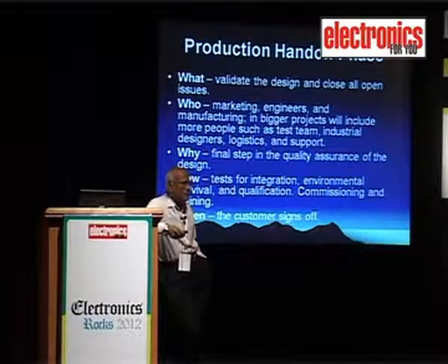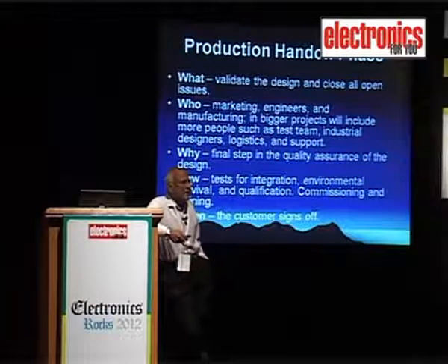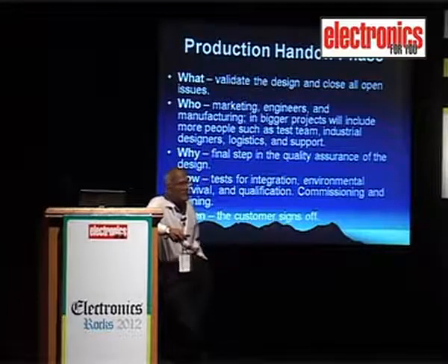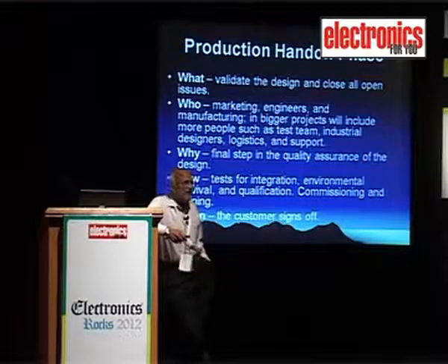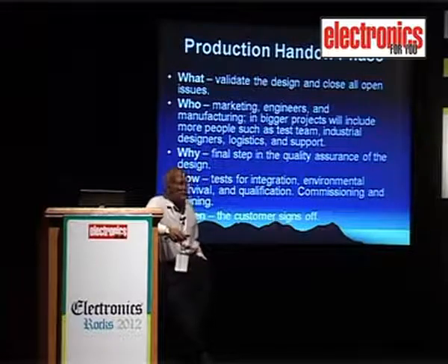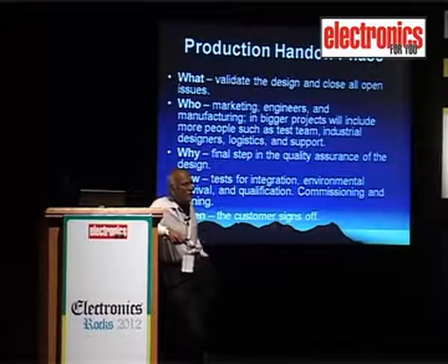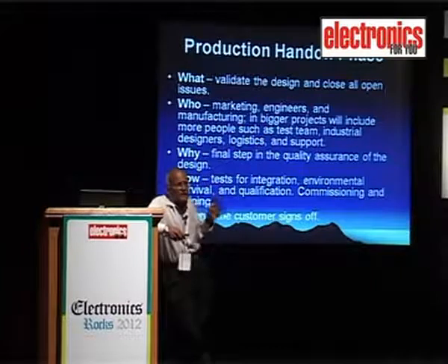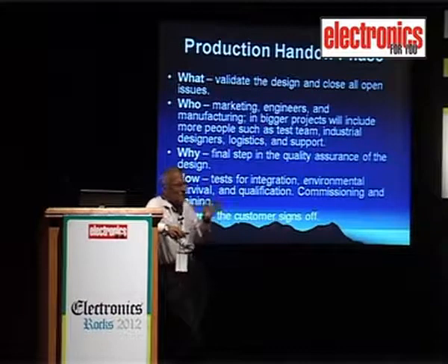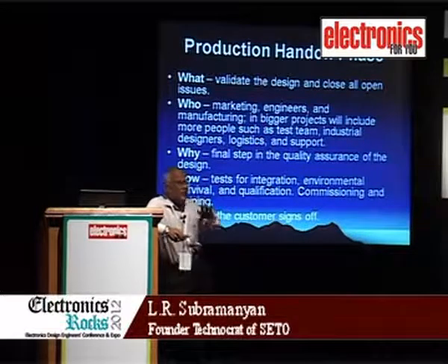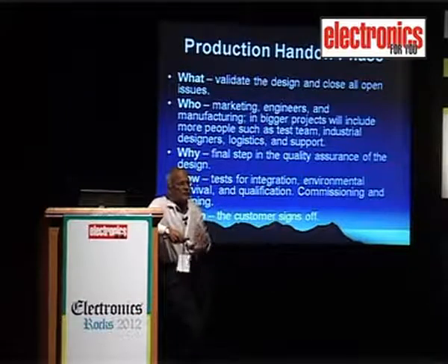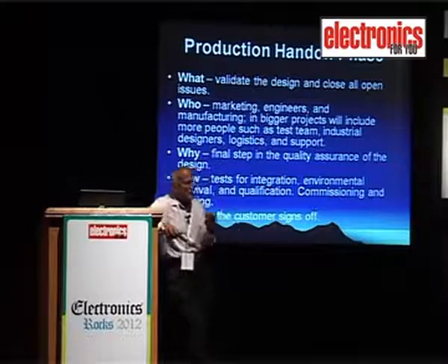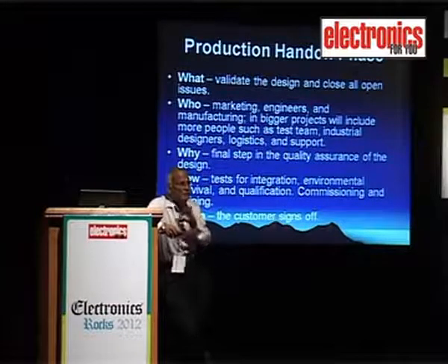Most of us would have to use, as part of our power supplies, electrolytic capacitors. Unless you use highly reliable electrolytic capacitors, normal capacitors that you would get in the market have a shelf life. If you say you have got a 100 microfarad capacitor, when the manufacturer gives it to you, he has formed the film inside, so it is around 100 microfarad. The tolerance for electrolytic capacitors is minus 50 to plus 100%. That is, if it's 100 microfarad, the capacitor could be 50 microfarad, it could be 200 microfarad.